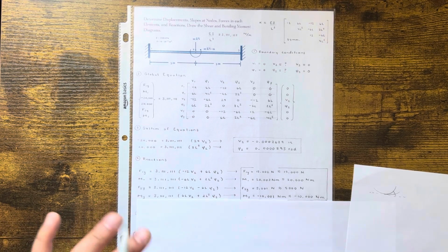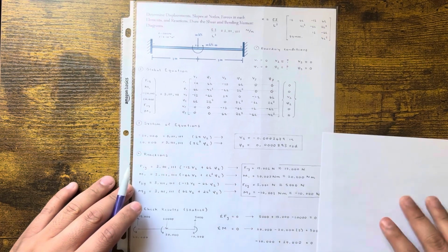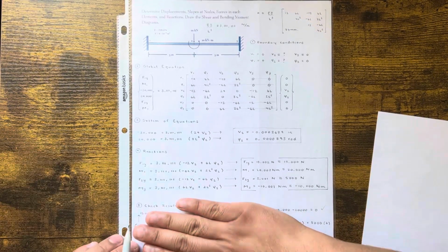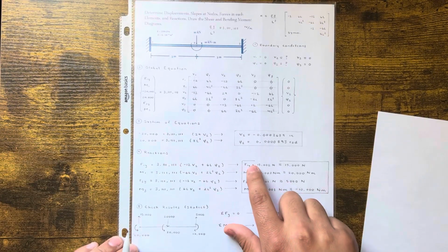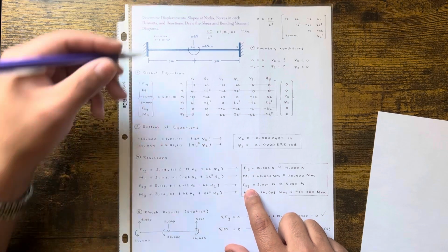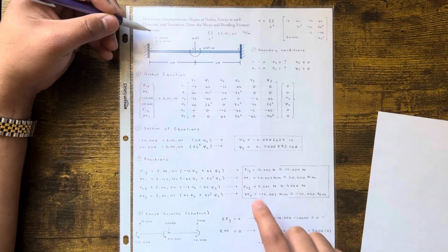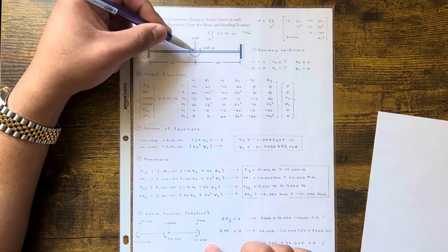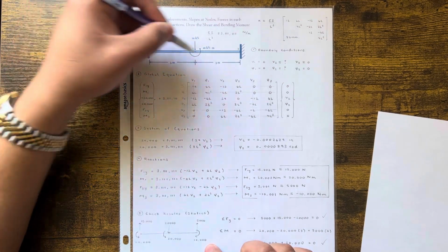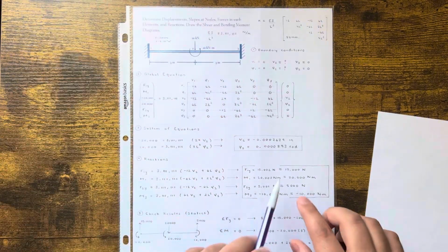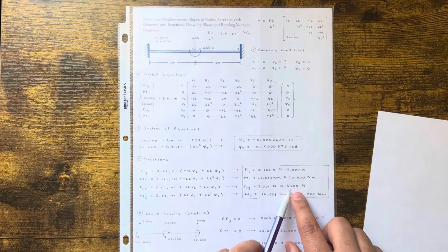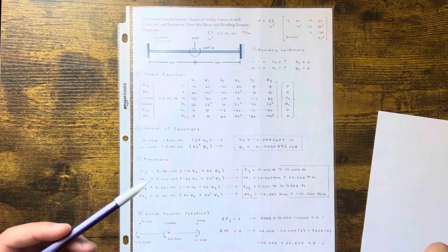Now these we could somewhat verify. Just use statics, right? Before we go to statics, just look at the numbers for a second. F1y and F3y. Summation of forces in the y direction. This is quick. You don't even need to write this down. You have 20,000 going down, so that means you have 20,000 going up, right? Is that true? Yeah. 15,000 going up at node 1, 5,000 going up at node 3. That's 20,000. That makes sense.